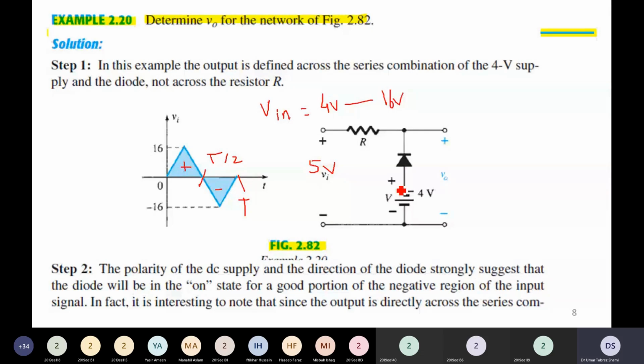Reverse biased. Why will the diode be reverse biased? Sir, when we give a positive half cycle of 16 volts, there will act a battery, and this battery will be parallel to the 4 volt battery, and 16 minus 4 is 12 volts, and when we replace a 12 volt battery, it will be having a reverse bias condition. तो ठीक है, concept आपका ठीक है, but